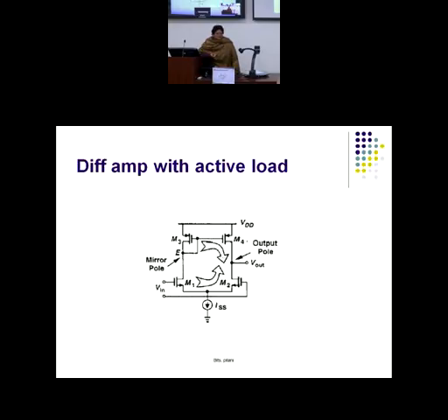R of a signal source. The signal source is usually not coming out from an RO of a MOS device. From a signal source like a function generator, they usually have a 50 ohms kind of inside resistance. 50 ohms, 100 ohms. Have you seen the ratings on the function generator? It's usually very small, so our signal is going to be very small.